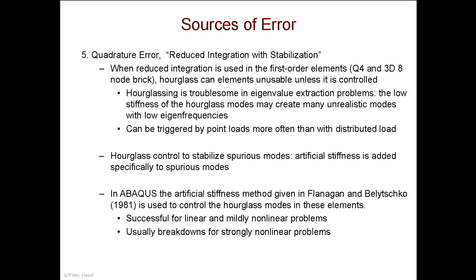So if I was you, I'd run your model, right? Exaggerate the plot 10 times. And if nothing is moving, you know there's a problem. I mean, right? This one is locking, as an example. But that alone is not enough. You have to do some hand calcs to get some confidence. Or do some mesh refinement studies to gain confidence in what you're doing. Okay.